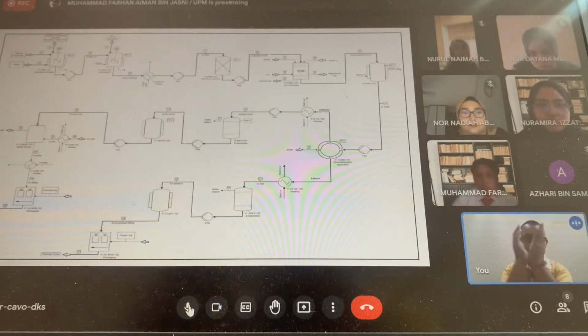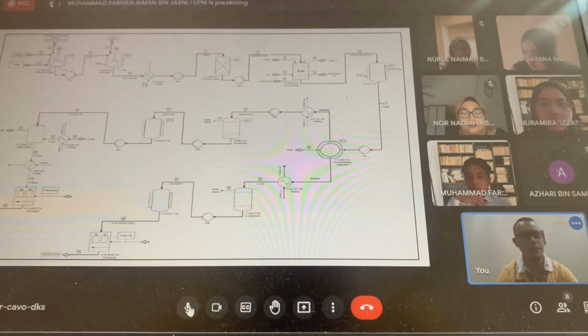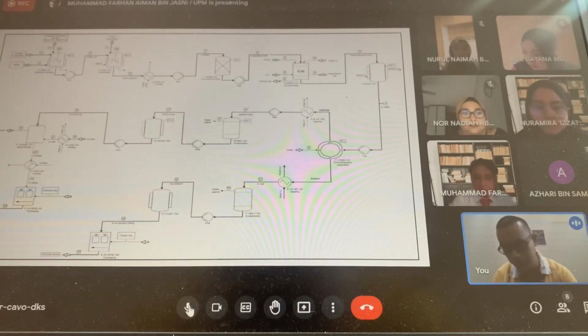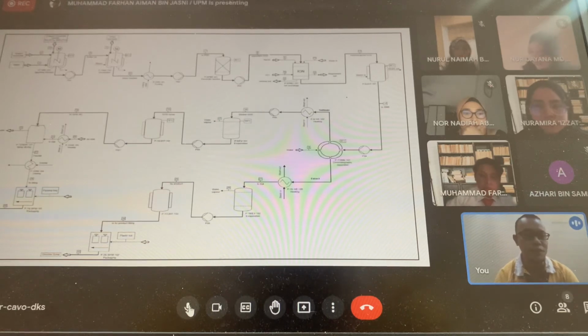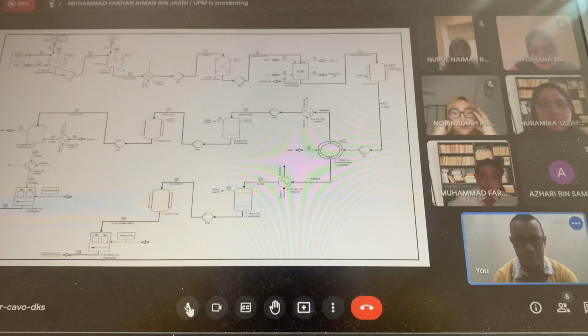Let's say you're filling the powder until it reaches the load cell. There is a sensor going to the PLC. So let's say you set the set point at 10 kg, right? When it is enough, at 10 kg, they open the valve and dump it inside the bag or pouch, alright? So based on the drawing I saw, make sure next time you put in the instrument. This is the more important thing where you can control the weight of the product. Okay, the rest so far I see everything you have, right? Okay, next please.